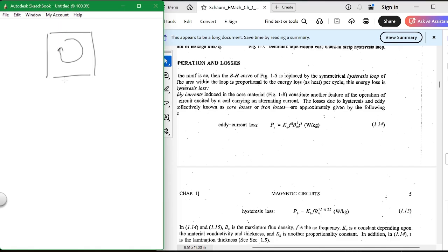Now that can be good or it can be bad. If you use the circuit that actually induces this, you can do all kinds of things with it. For one, you can have a proximity switch, which is a barrel type switch. A prox switch can have a coil that induces an eddy current on a piece of metal. Then that eddy current can induce a current back on a secondary coil in the same device.